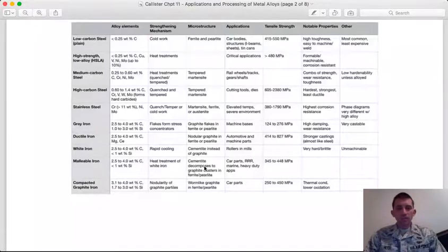What that allows is the cementite gets a little bit of time and temperature to take on more of an equilibrium state, where the phase diagram would indicate that you don't have cementite, or at least as much cementite at that region, and so this allows some of that to decompose and form graphite clusters, and so that allows it to become a little less hard, a little more workable, as its name would indicate, being malleable.